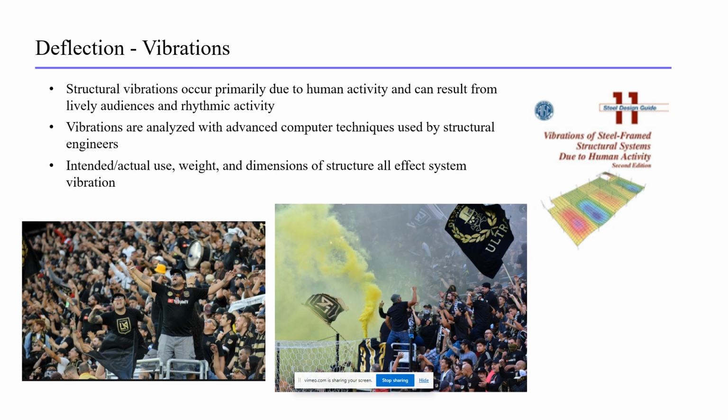Other important serviceability related issues include dynamic behavior and general durability. Dynamic concerns primarily deal with vibrations of floor systems. We talked about that briefly with the deflection. They're essentially accelerated deflections or movements that occur with occupants and will occur in any system based on the movement of the occupants and the structural properties of the system. More lively activity with more flexible structures may result in user discomfort. Considerations are made so that people will not feel uncomfortable when the system is in use, and there's various acceleration limitations proposed by standards to mitigate that uncomfortable feeling.